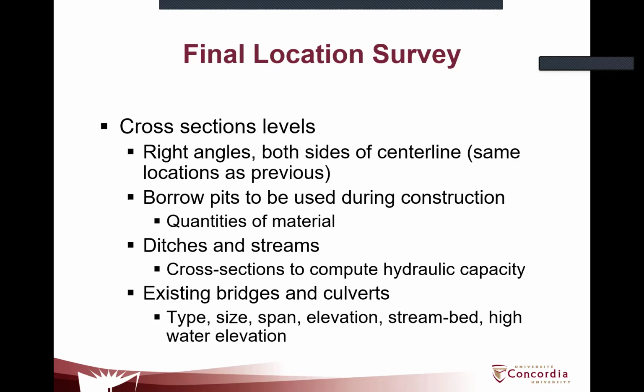You need to also locate where the different ditches and streams of water are, and calculate the hydraulic capacity of those streams, because the runoff water that the road will collect needs to go into ditches and then eventually into streams like rivers and creeks and so on.